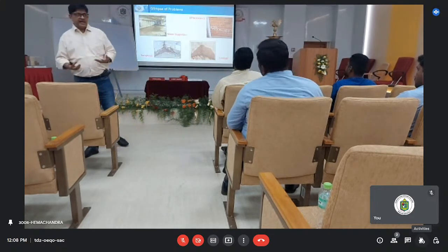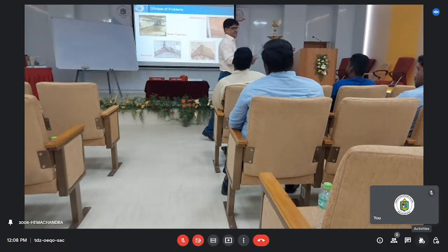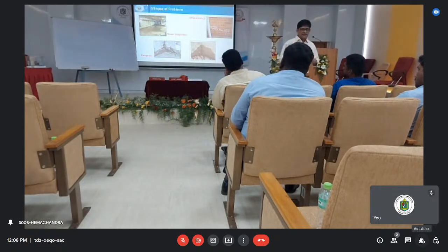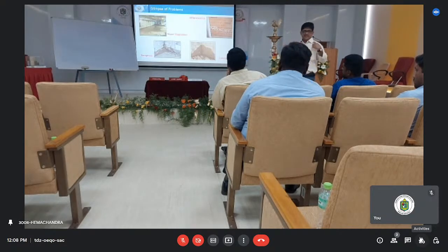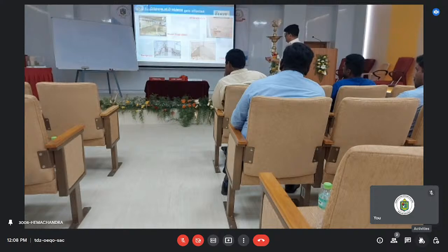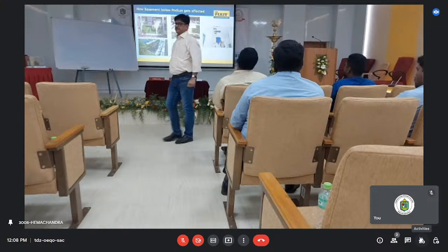If it is a brick or masonry structure, the salts inside the bricks come out with the water and then cause a problem. And that is a critical problem inside the houses. Dampness can appear in corners and areas. You can have leakages, water coming out, all those sorts of problems, which is very common in the basement. The basement problem also arises because of the facilities on the top.